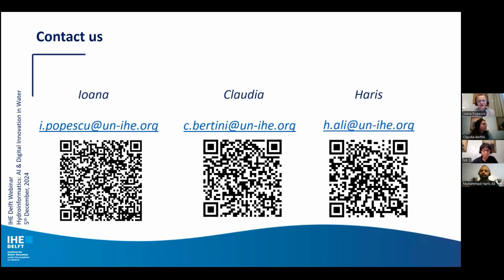I hope that I understand the question well. We use the remote sensing data for input and not for model calibration and validation. In order to do the model calibration and validation, we had to extract the water levels of the lake and deduce what the inflows into the lake would be. Then, based on those inflows, we could see if the hydrological model, which was an IHE HMS model, is giving the same discharge at the outlet. I hope that this was the question.